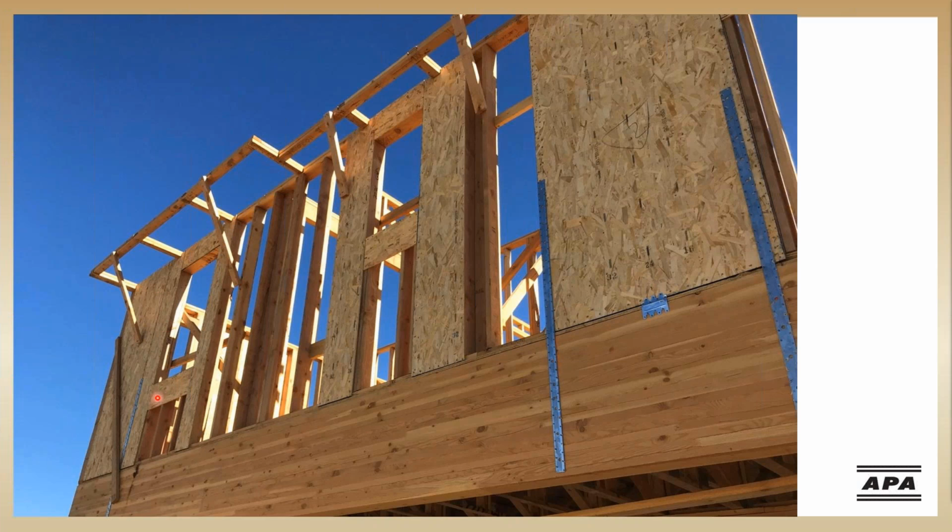Now, from the strap location you see here, you can see where the panel that they're counting is actually ending. So here we're providing an extra foot of sheathing, but we're not getting any credit for it. And this is one of those cases where I think we want full credit for the sheathing we're providing. So just think about what you're really saving by only counting a slightly narrower or slightly shorter wall length.